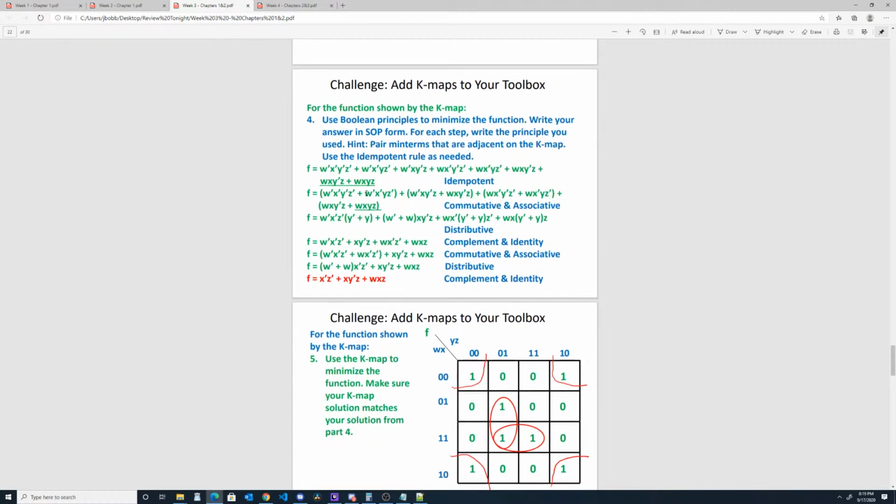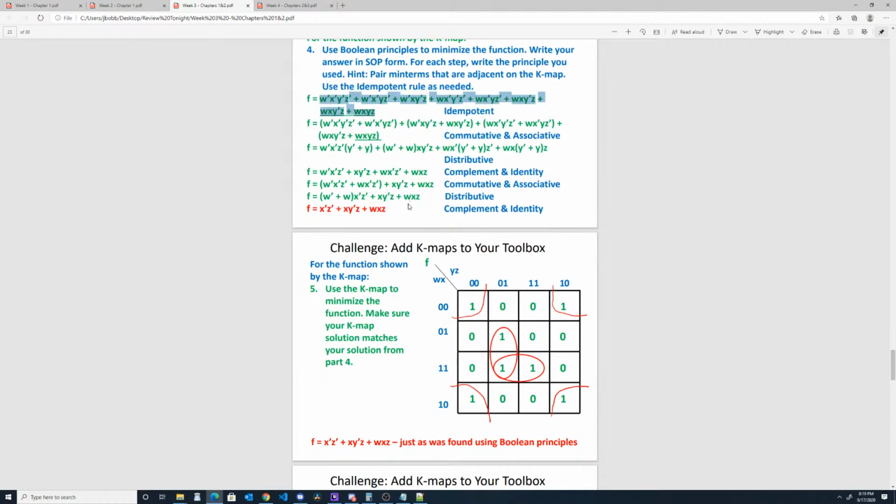And so we have all our minterms here. This is in canonical form already. So what are we going to do? We're going to populate the minterms, right? This is all zeros, so 0, 0, 0, 0 is right here. We're going to put a 1 right there. What's the next one? This is 0, 0, 1, 0. So I'm going to find 0, 0, 1, 0, which corresponds to this minterm. I'm going to put a 1 there.